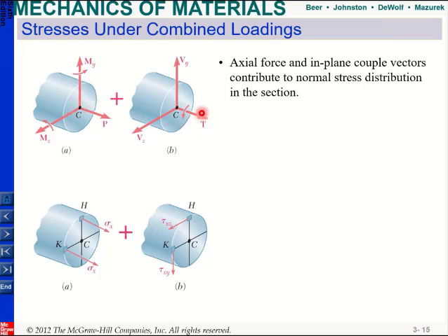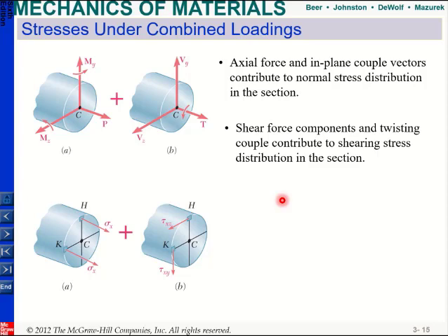Okay, and then also we might have a shear force along y direction, we might have a shear force along z direction, plus we might have a torsion. And these shear forces, they create shear stresses, and torsion also creates a shear stress. So basically these three, they will create normal stress, and these three, they will create shear stresses. So which means that at each point I need to determine what are my shear forces and shear stresses. And it's also important the directions.